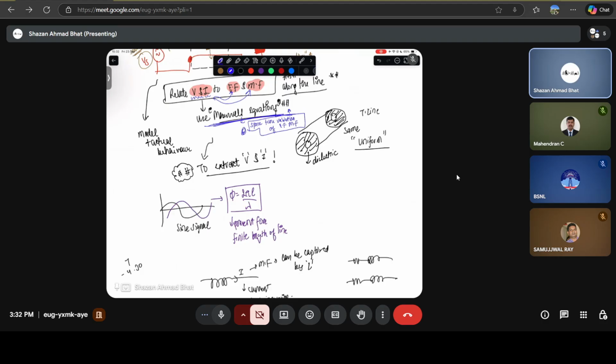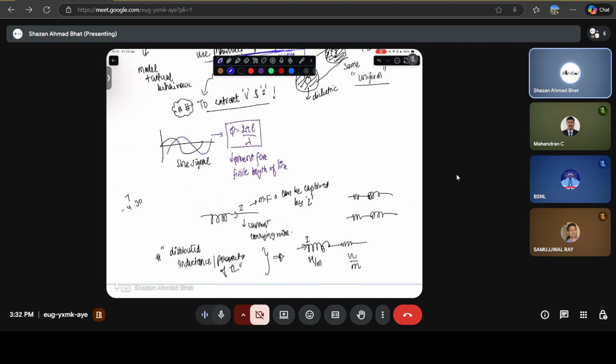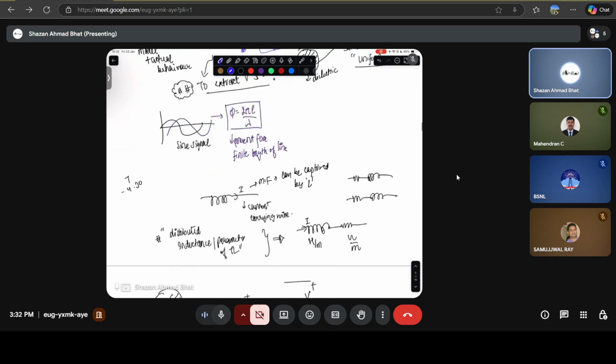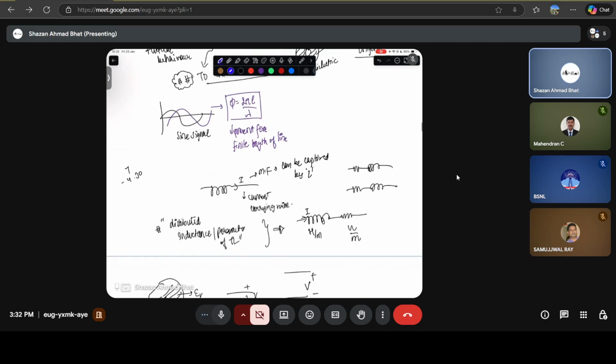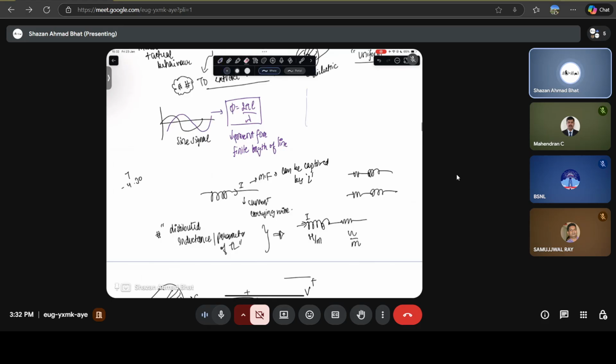Now, for example, the phase I was talking about. If you have a transmission line, there's a phase associated with the waves, which is a function of the length scale, this length. And this phase is given by 2 pi L over lambda. So this is the phase associated. Where does this come from, by the way? This is basically the delay.